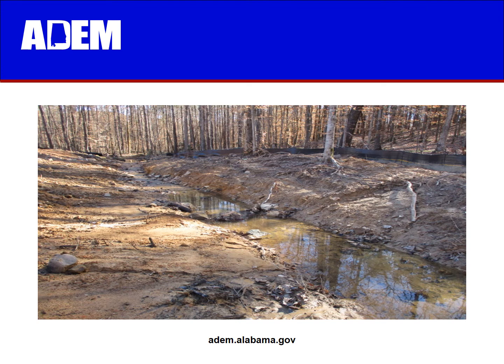Another common non-compliance item is not adhering to the minimum buffer requirements for creeks, wetlands, and other waterways. These buffers can be important natural methods of preventing soil and sediment from reaching a local creek or wetland area.